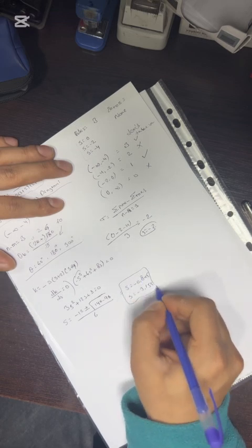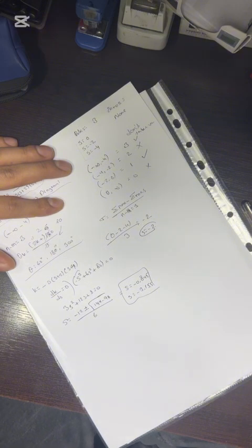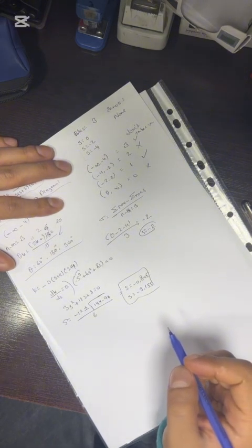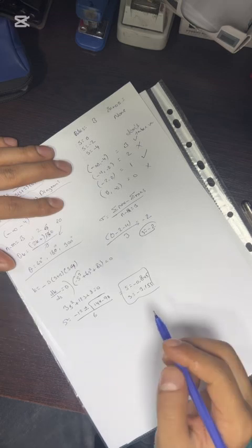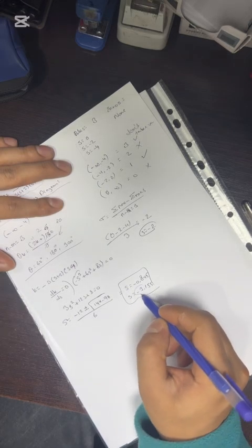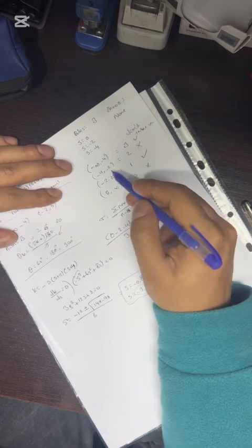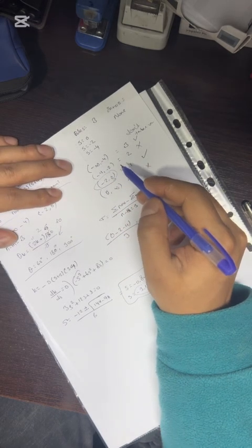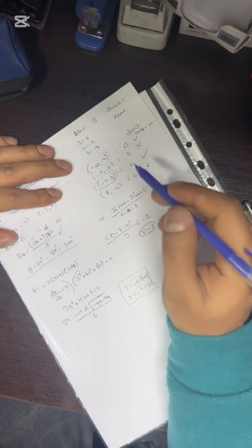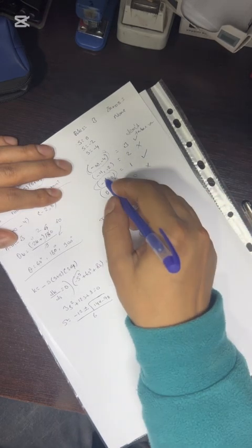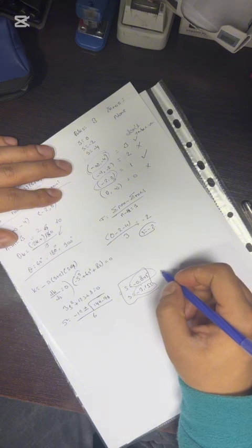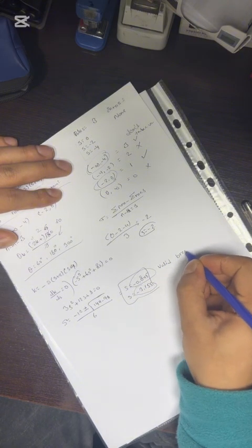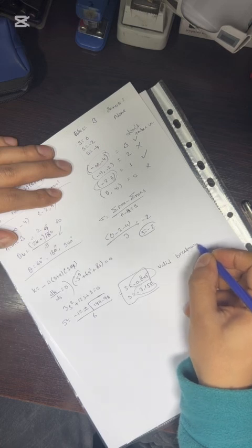These are the roots of this function. As we know, the point at minus 3.15 is not available, because the root locus is not between those points, but the point at minus 0.845 is available between this segment. So this is our valid breakaway point.